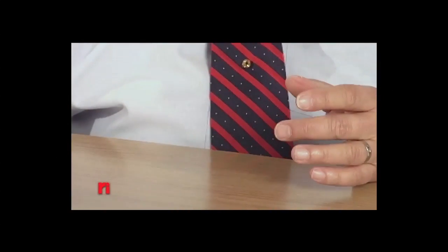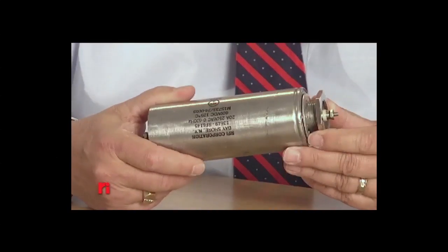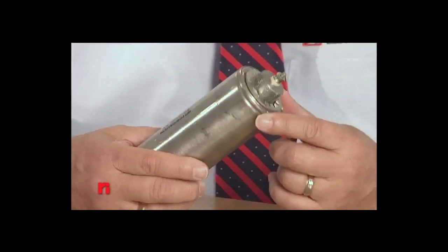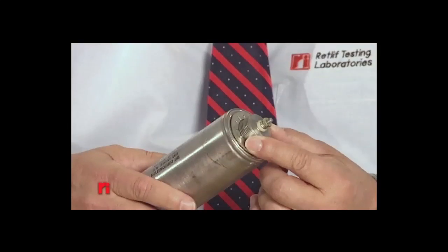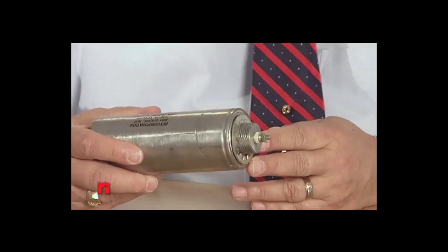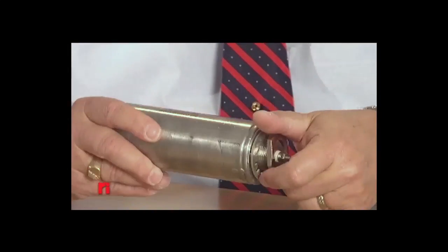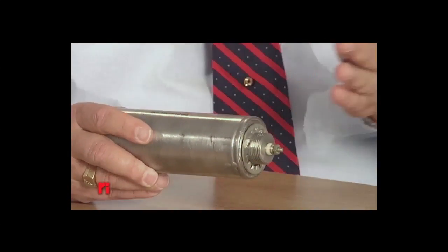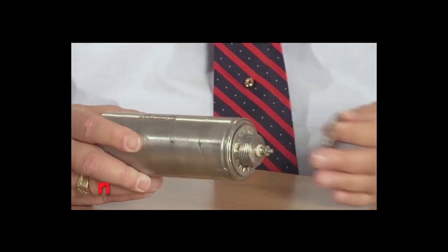To address this, we can look at mil grade type filters or mil standard type filters. What I have here is a tubular filter, and the beauty of these types of filters is how they're mounted. This particular filter comes with a threaded neck, and the concept here is you're going to drill a hole in the outer wall of the piece of equipment and mount this filter through that hole, secure it with its appropriate hardware, and then you have a metallic metal shield between the input and the output, which provides much better isolation and eliminates the coupling.